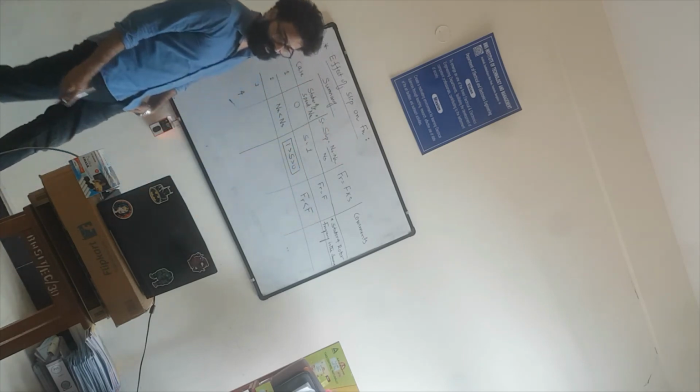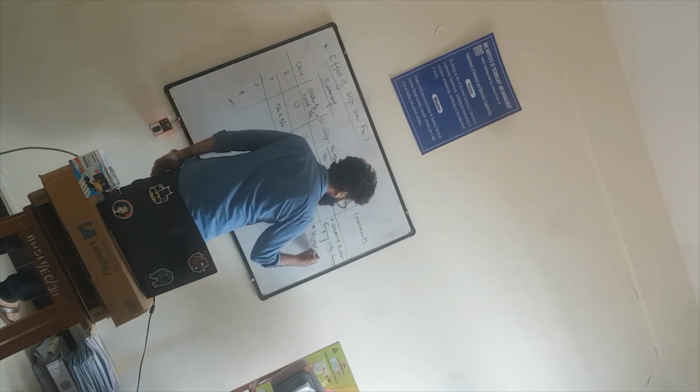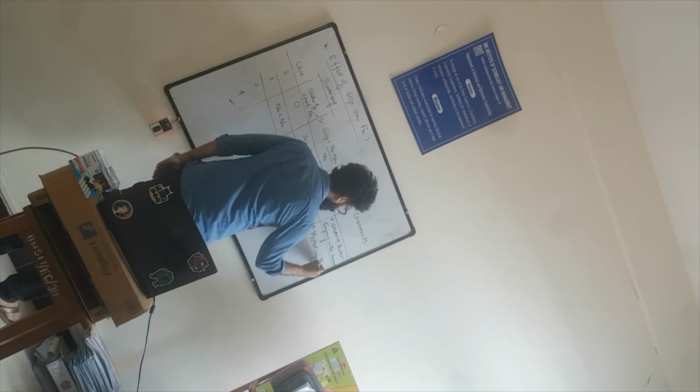Due to which the rotor frequency Fr is less than the stator frequency F. And what do you call this particular operation where the rotor speed is less than synchronous speed? This particular operation is called motoring mode.